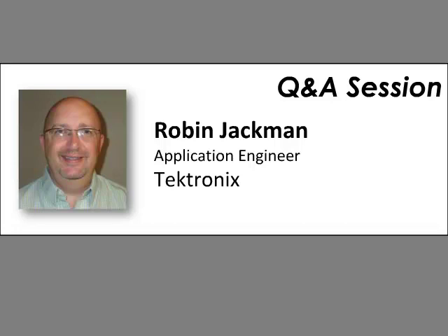Okay, that's great. Thanks, Robin. Our next question is on the MDO4000. Can we control the length of spectrum time? On the MDO4000, spectrum time is controlled by manipulating the span and the resolution bandwidth controls.